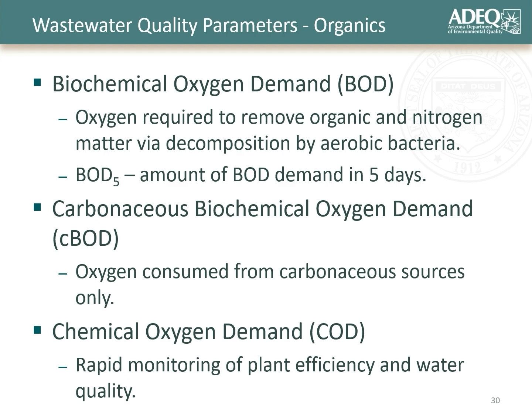And so sometimes this type of test is used in the short term to understand your plant operations and to be able to make adjustments to improve performance before you can get the results from your BOD or CBOD test.